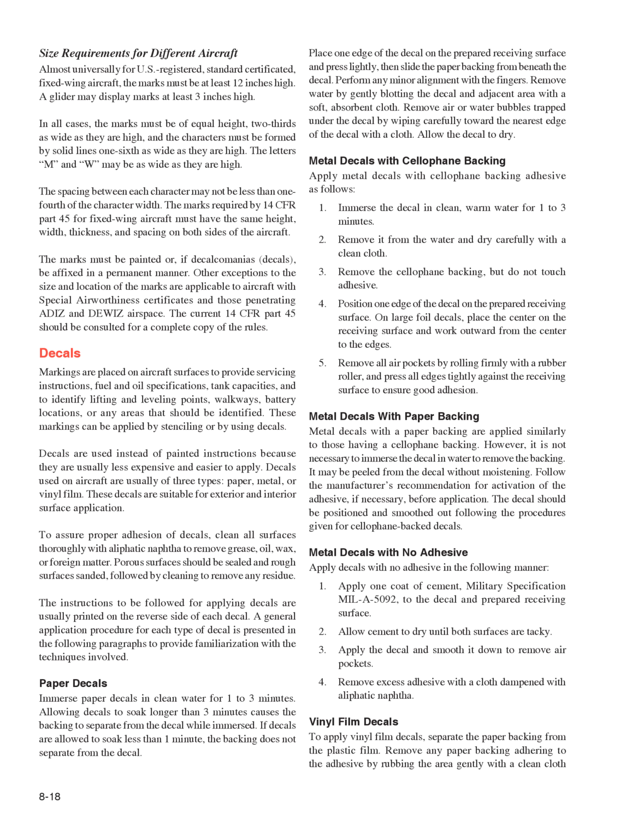Decals used on aircraft are usually of 3 types: paper, metal, or vinyl film. These decals are suitable for exterior and interior surface application. To assure proper adhesion of decals, clean all surfaces thoroughly with aliphatic naphtha to remove grease, oil, wax, or foreign matter. Porous surfaces should be sealed and rough surfaces sanded, followed by cleaning to remove any residue. The instructions to be followed for applying decals are usually printed on the reverse side of each decal.